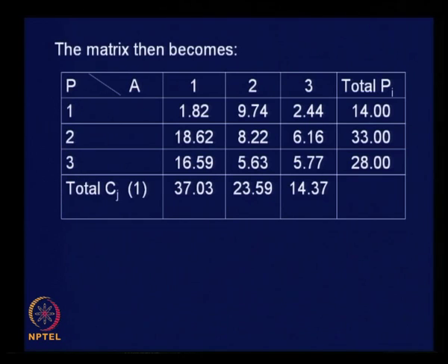We must resort to some iterative process to bring the trip attraction values back to the original values, simultaneously holding trip production values unchanged. That will be held because it is in the model framework itself. Let us see how to go about doing this.